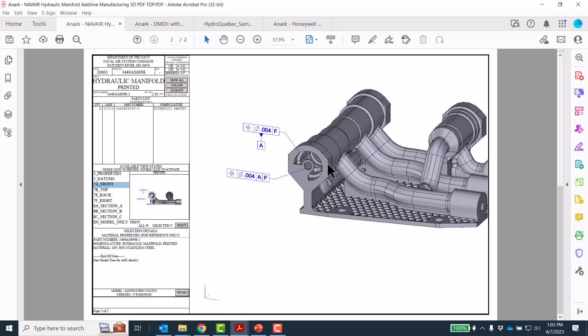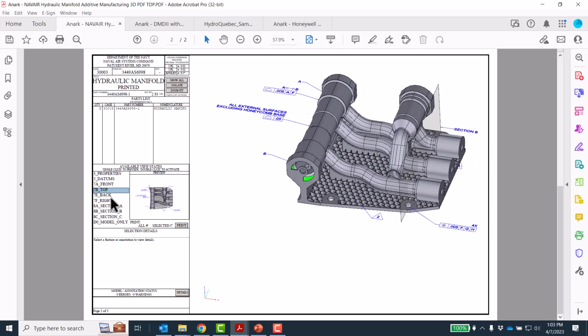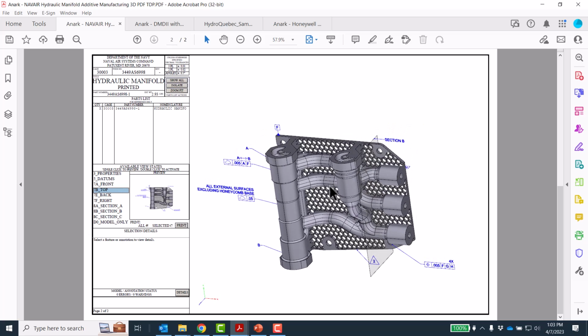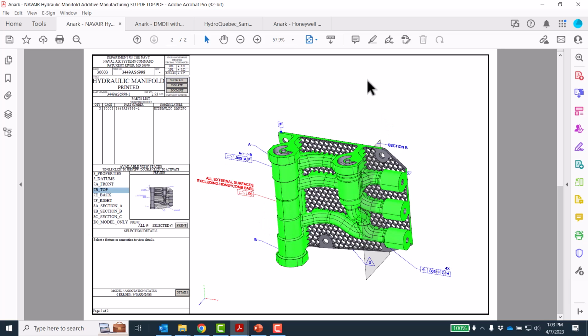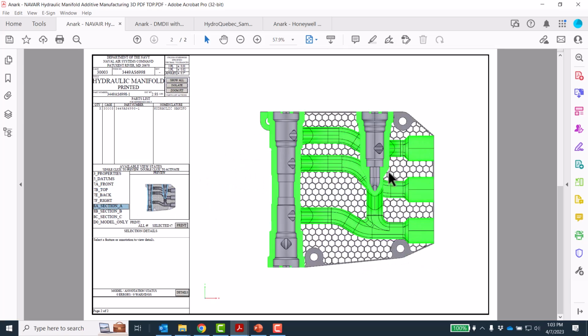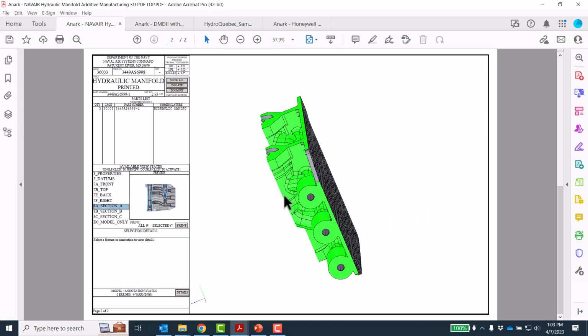And this is a Creo model from a few years back, but you can see that we're retaining and publishing the GD&T that came from the original views. We're capturing the different views. We're cross-referencing the relationship from the GD&T to the underlying geometry according to the ASME Y14 standards. We can do things such as cross-sections and maintain cross-sections.